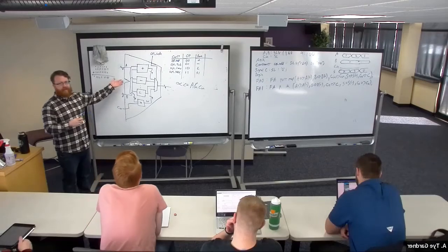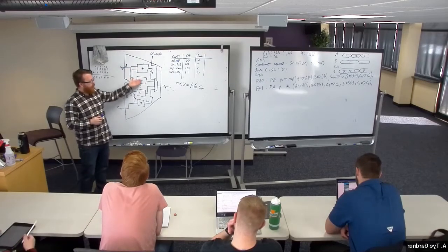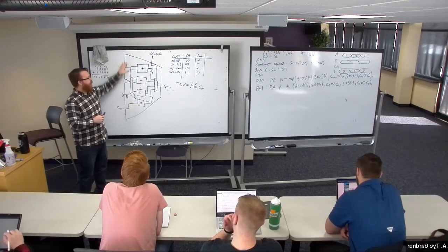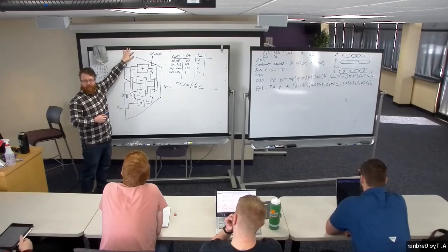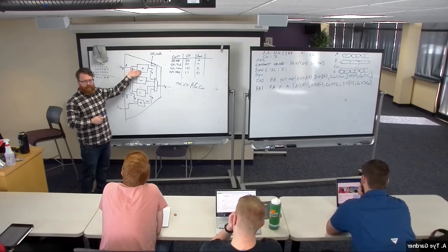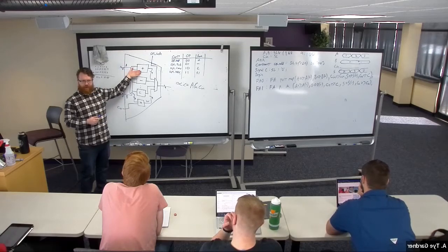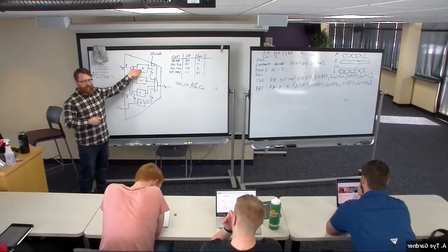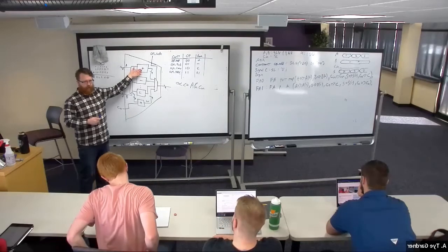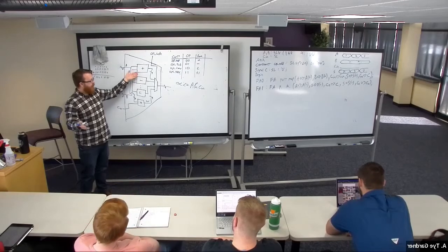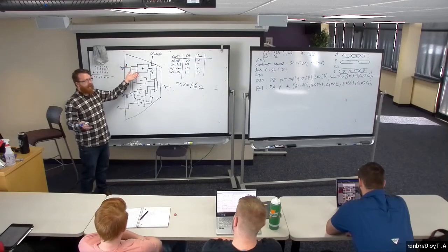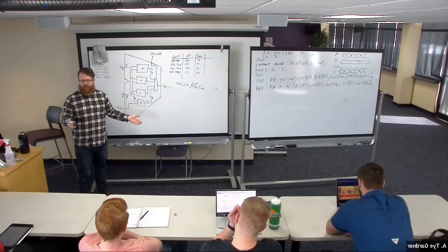Anyways, that's an ALU. You're going to write a couple different components. You're going to write a top level module called ALU. You're going to declare these components inside of them, right? Hierarchically. Inside of this might be the full adders that you've already added, or 2 4-bit adders. So it's going to have a couple layers of hierarchy. And then connect them up with named signals, right?